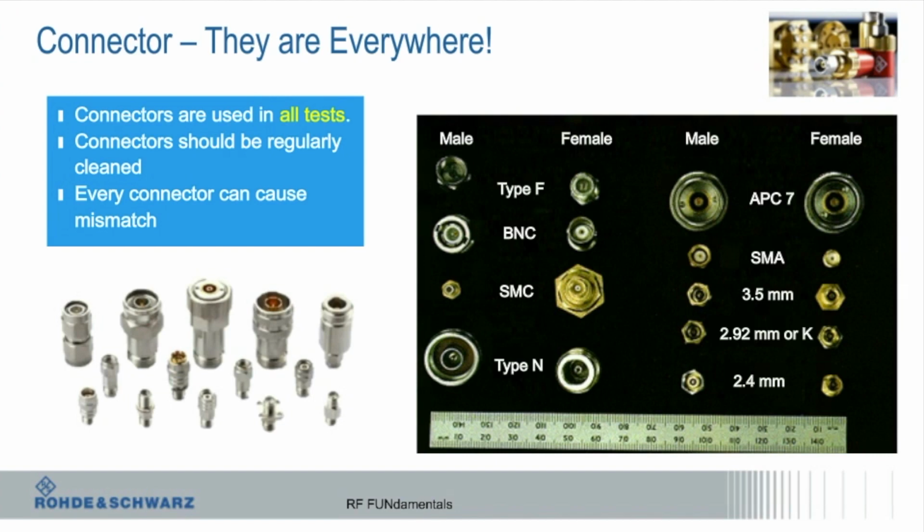Question? You're saying that the thread pitch on all like the SMA, the 3.5, that's the same exact thread? No. What I'm saying is these two will thread, right? And this one and the 1.85 will thread. Did you say the SMA will also thread? SMA technically will, but again, this isn't a precision connector. So it does happen where you plug this into this and it damages it. More often than not, what happens is that center pin, because it's not a precisely toleranced center pin, might be offset and not go in correctly and then bend the pin.